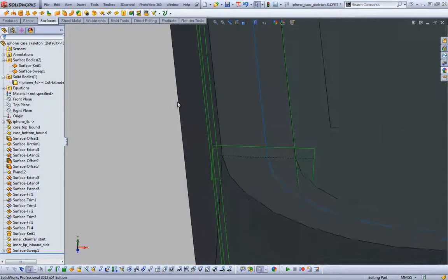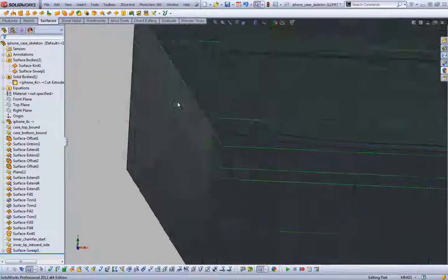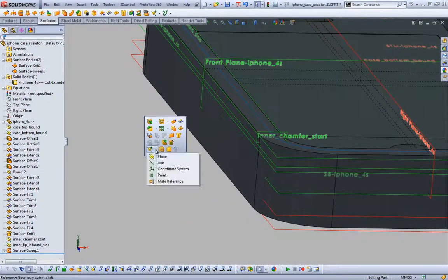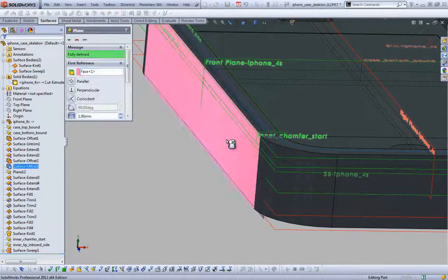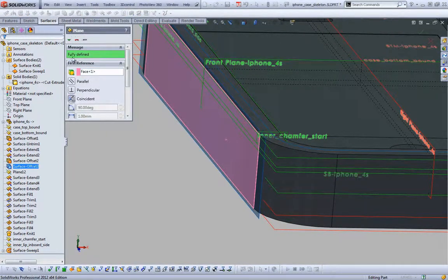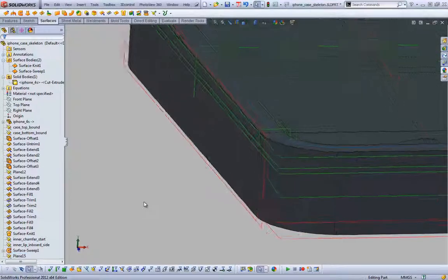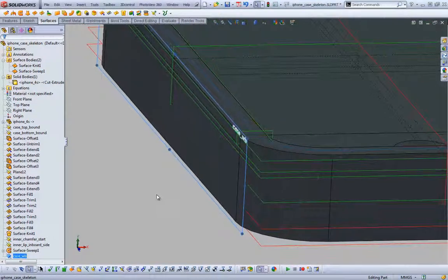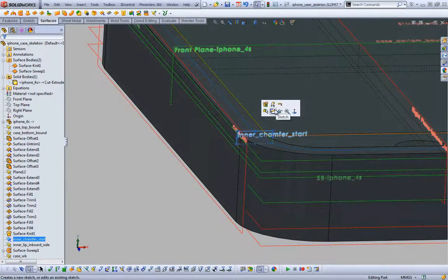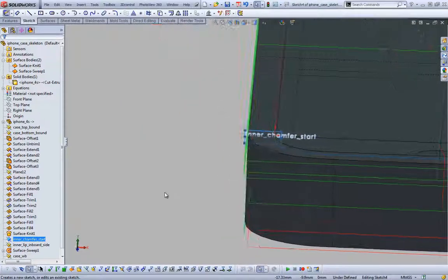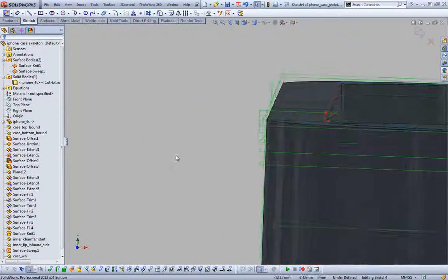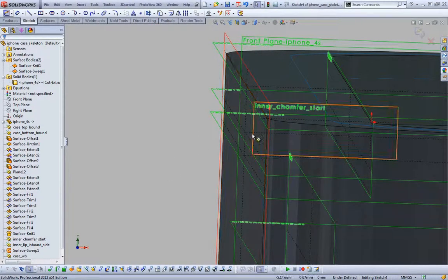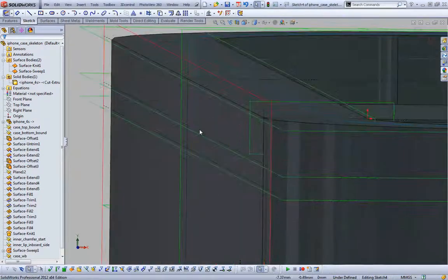after. Let's see, I need a plane defining the outside. Again, SOLIDWORKS doesn't allow using a perpendicular surface, geometrical surface. So this is going to be the case. SOLIDWORKS unfortunately doesn't allow using a perpendicular geometric surface to a sketch as a reference. It won't even let you pick it. It wants to use the edge.